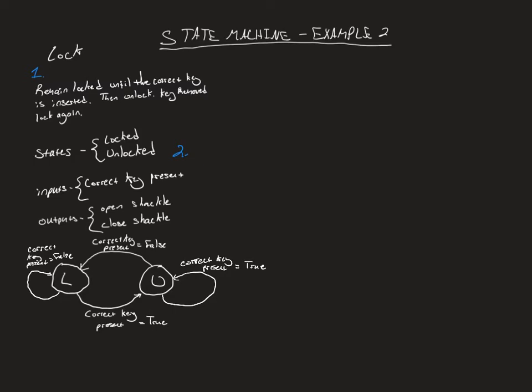So that's a common thing in state machines that you'll see: you don't just see transitions away from the current state, you'll see transitions back to the state that you're already in, in situations where an input could potentially cause a transition or an input is changed. So, for instance, this is a situation I can imagine happening.